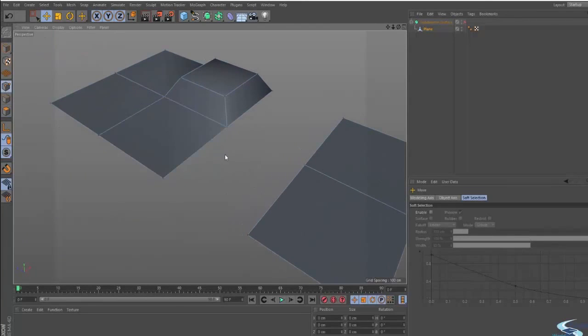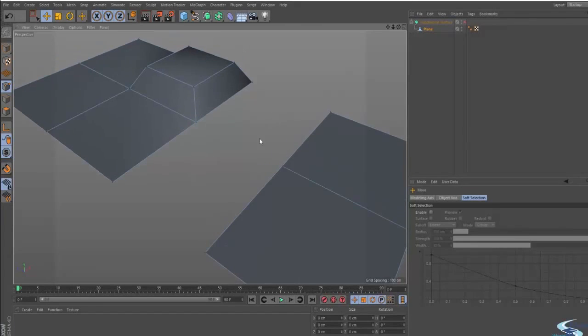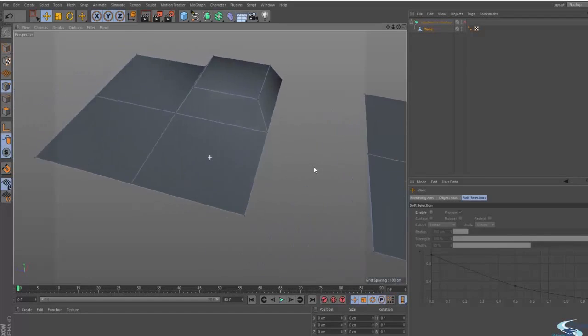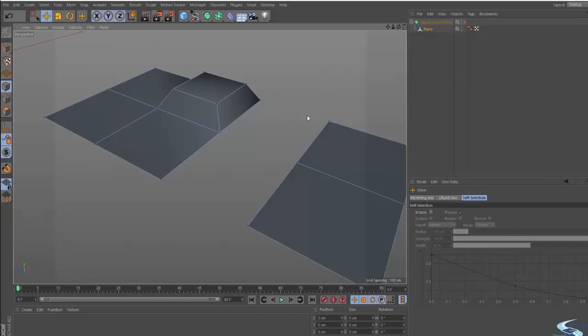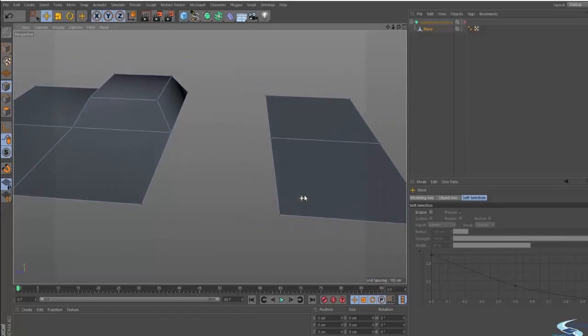Then we actually need to somehow take this vertex and this vertex and weld them together, make them into one vertex in this position, or we could create some geometry that's in the middle. So we can either weld the vertices together in pairs, or we can create a bridge between, like create some geometry that covers this gap. So let me just go over both techniques.